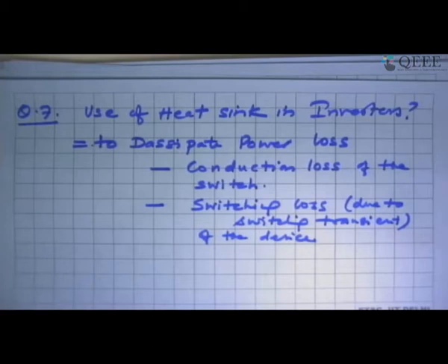Depending on the condition of the battery, if it is highly discharged, the rate of charge should be different, and when it is close to full charge, the rate of charging should be different. To understand that, we have to understand the SOC of the battery. SOC means state of charge of the battery.